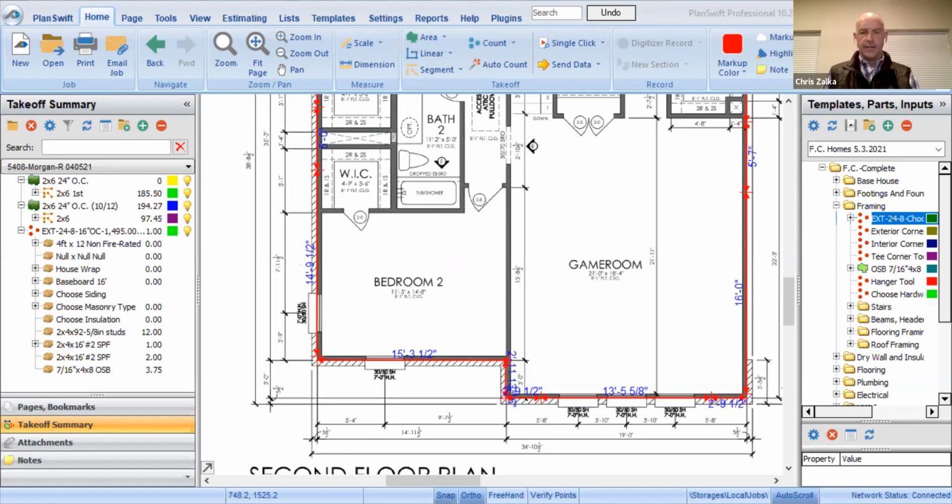Yeah, I mean, the builder in Minnesota gave their plan to a local lumber yard and they did the design, and pretty much what they did is, I want to call it old school. They see a wall and they put a beam under it, but usually it's always more cost efficient if you can carry a wall perpendicular with I-joist and just cut out beam material. And it was just not really value engineering it, not taking your time to see which way would be more cost efficient.